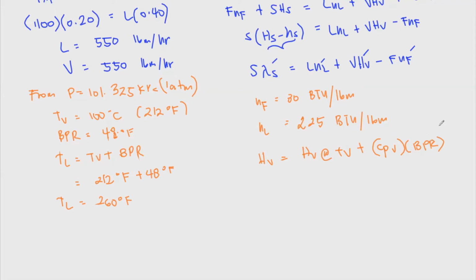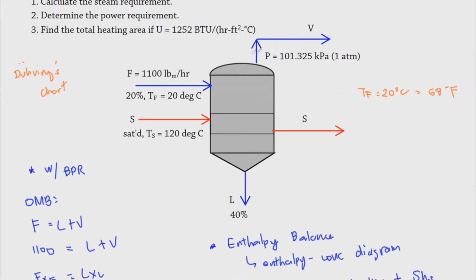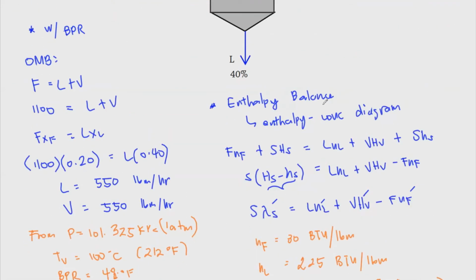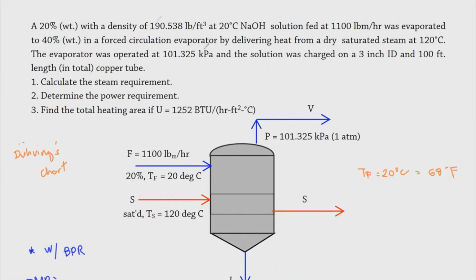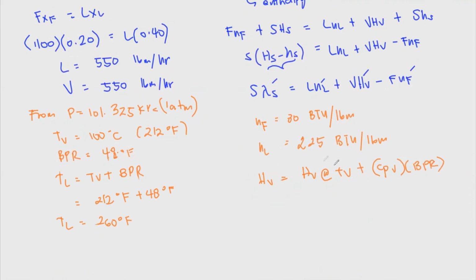So that happens again because during this boiling, we could see that the solution should have been boiling at 101.325 because that's the vapor chest, that's the operating pressure. But because of the concentration of this sodium hydroxide, and that's 20%, it gave us an increase in final solution temperature.